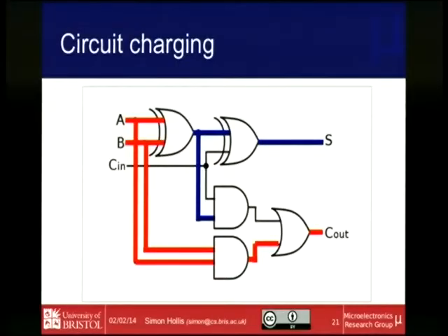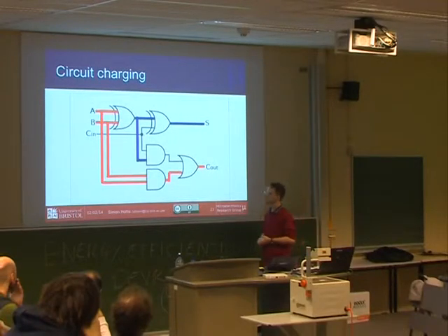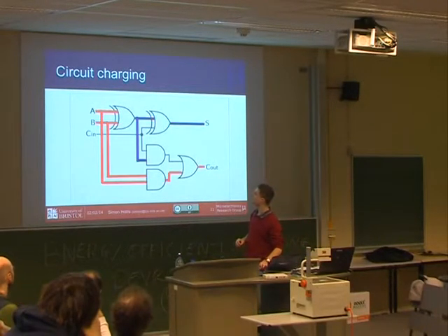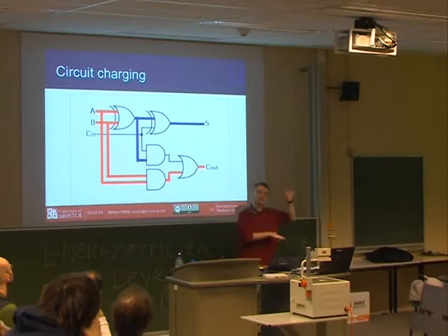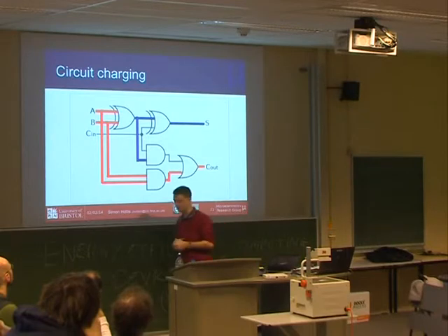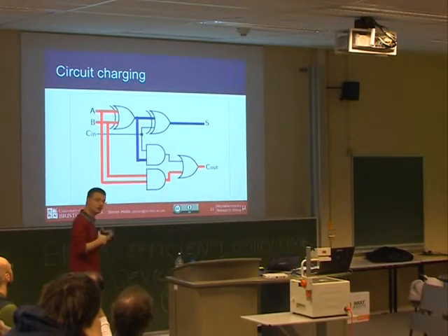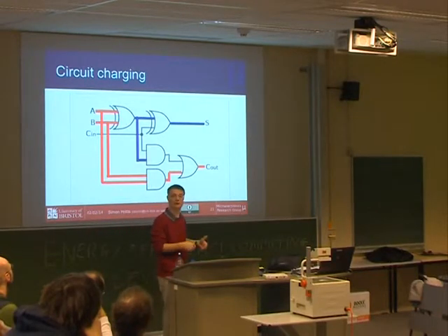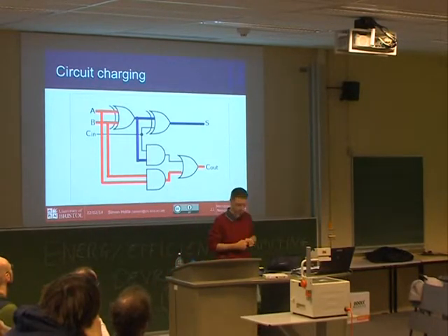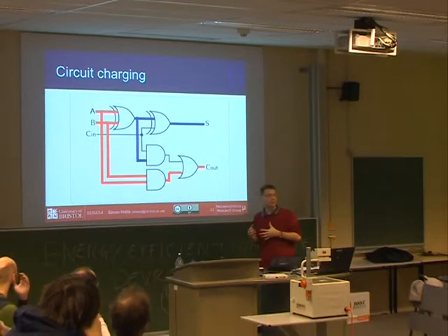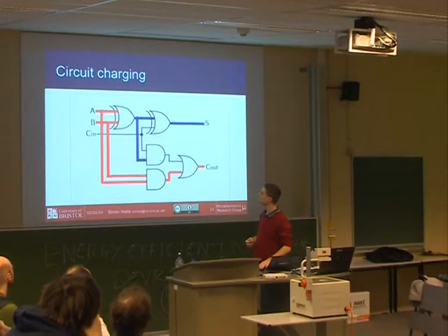We look at the output from that first gate. Once I apply another high input, it changes from red to blue, blue here meaning a low voltage. So the voltage there changed, and as it changed, it swung the full voltage of my power supply, whatever that voltage is, probably 1 volt in one device. And so it charged and discharged a capacitor by a volt. And so the microprocessor now consumes power. So that's the reason that we use the energy.